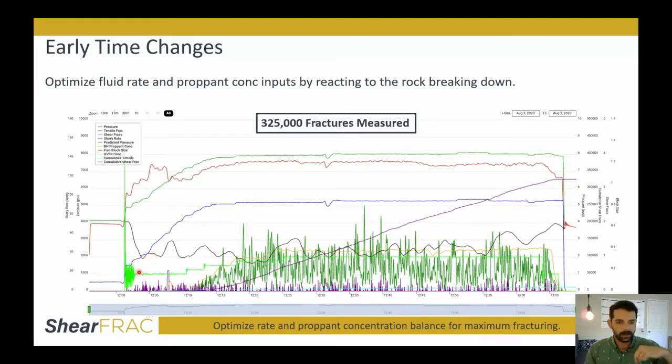So the beginning of the stage here is very critical. They ramp a lot slower when they're looking at trying to maximize shear fracturing. And that allows you to control that initial tensile fracture, and that allows you then to stress the formation far better than if you created a large tensile fracture and just this big void behind. If you can focus on that breakdown, you can avoid these fracture-driven interactions, but also it allows you to create more fracture surface area closer to the wellbore.